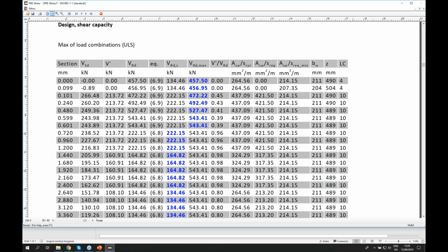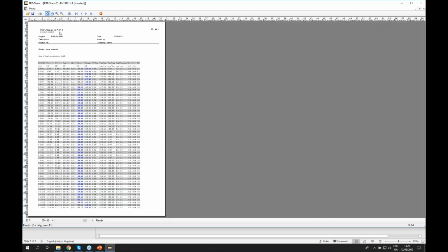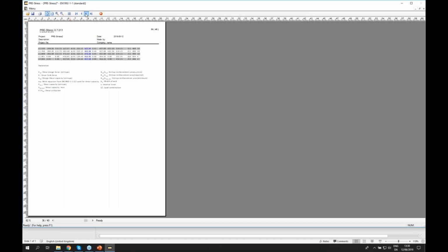Okay. So that means that the shear force would actually be small, and the required reinforcement for that force will be less than the minimum in the code. So even though it's less than that, you would still have to put it, because that's the requirement. Well, it's the code, the requirements for the code.